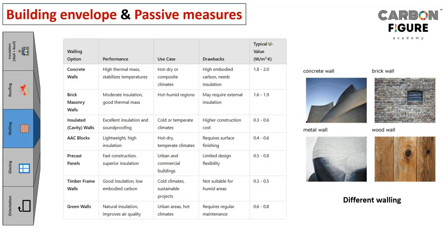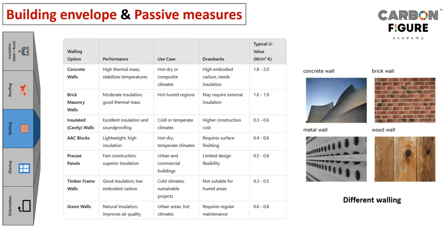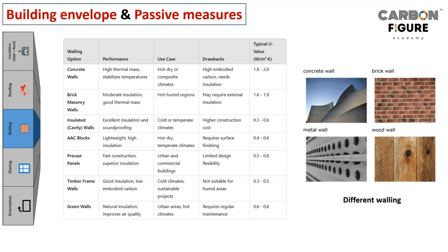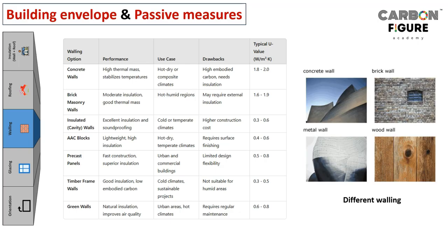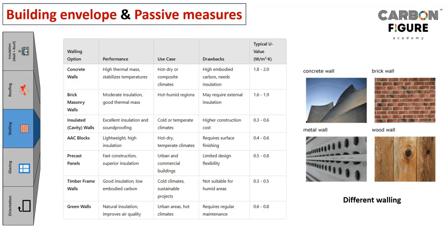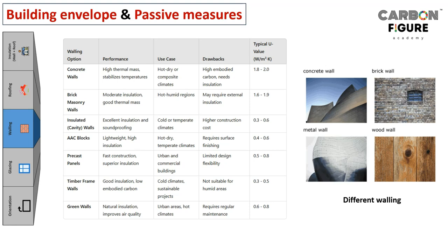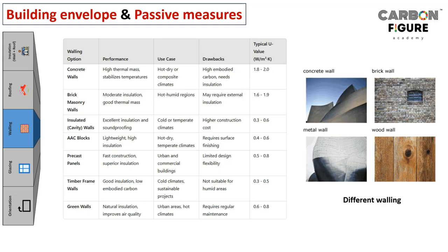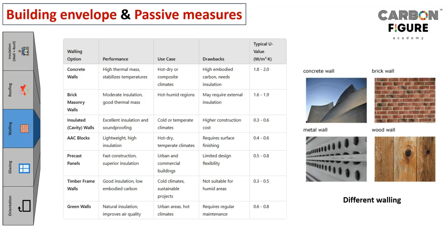The timber cannot be used everywhere, right? Even if you have affordability or availability, you can't prefer it, because it may pose some negative indoor comfort issues when you use it in wrong, inappropriate regions. That's why in humid areas, it should not be used, right? The U value is very good, 0.3 to 0.5.